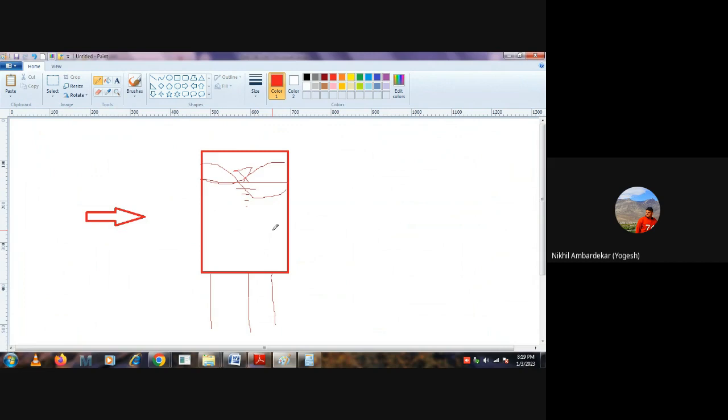Those are basically, if you see, the codal provision for the hydrodynamics. Okay. So convective mass will be, this entire pressure will be acting on the wall. So those are called convective mass. So if I want to try to draw what is called a free body diagram of this, so this is my wall. Okay. This is my wall.